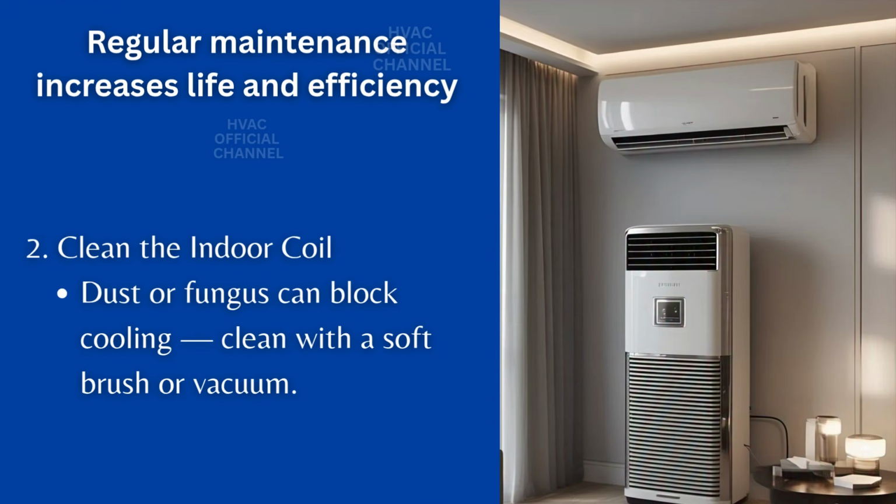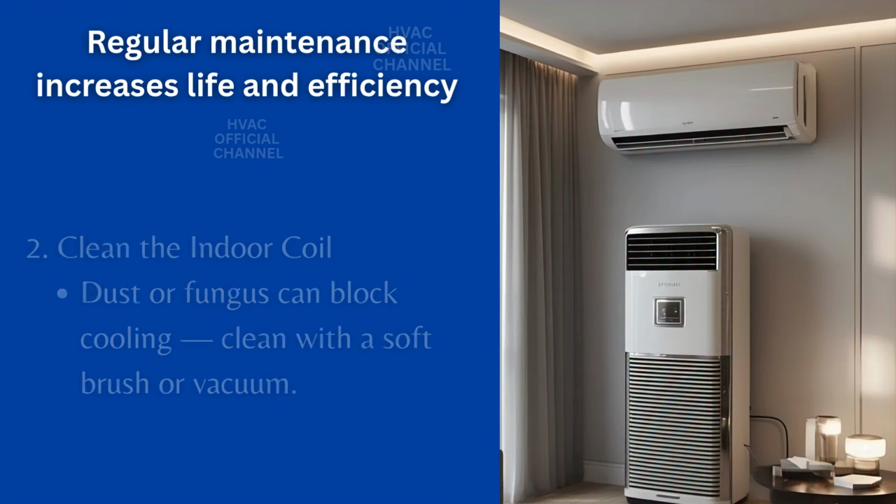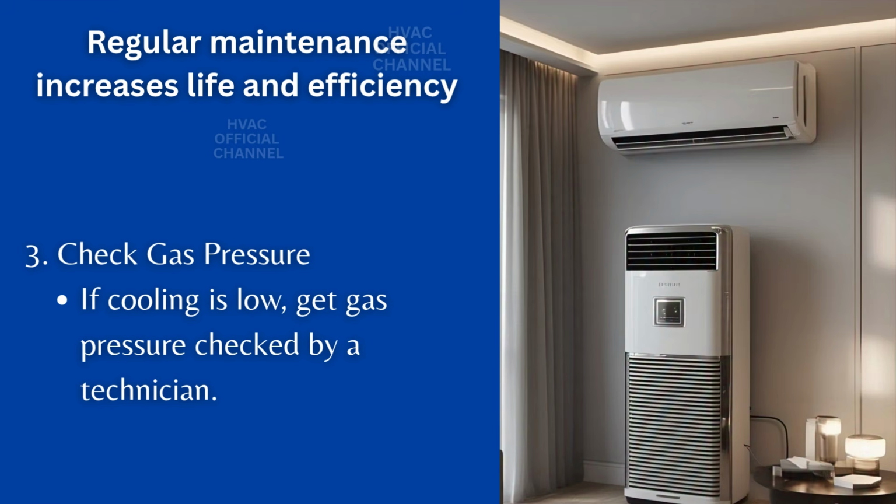2. Clean the indoor coil. Dust or fungus can block cooling. Clean with a soft brush or vacuum. 3. Check gas pressure. If cooling is low, get gas pressure checked by a technician.